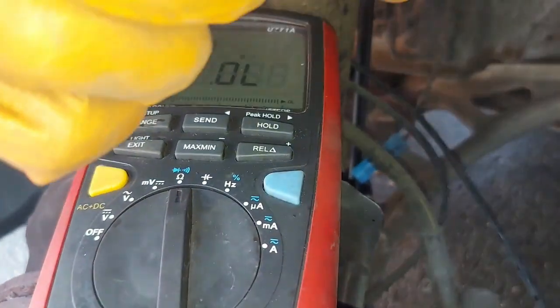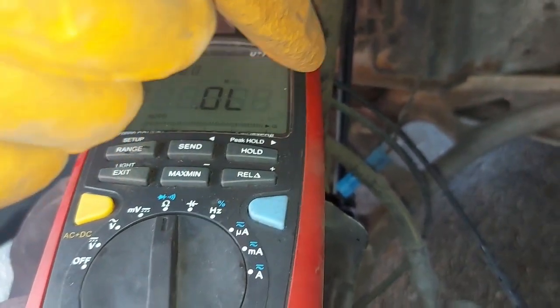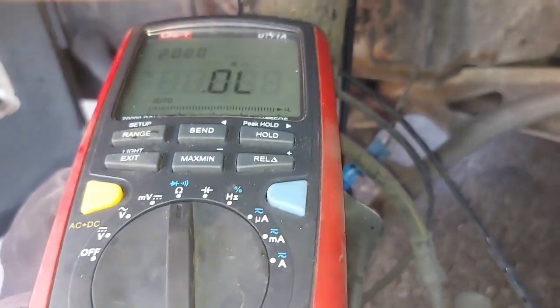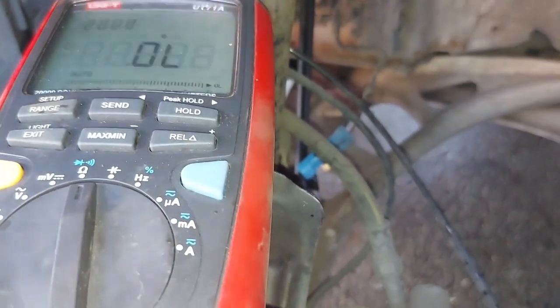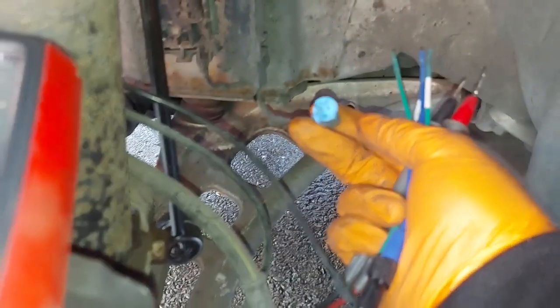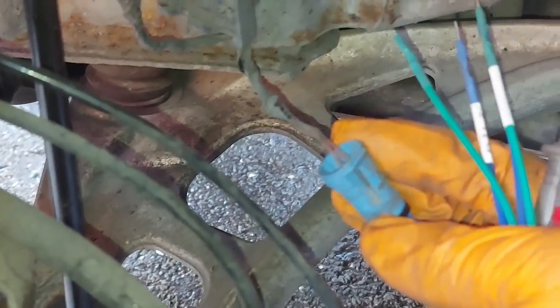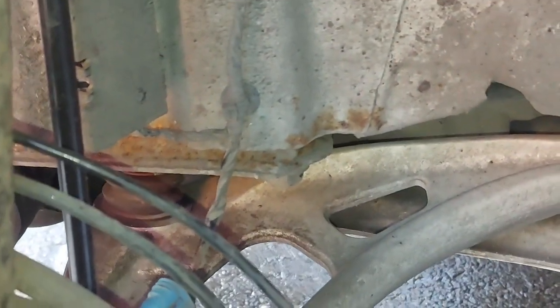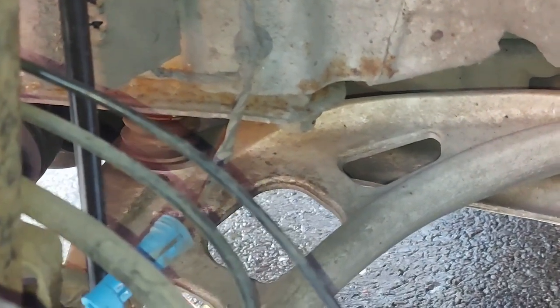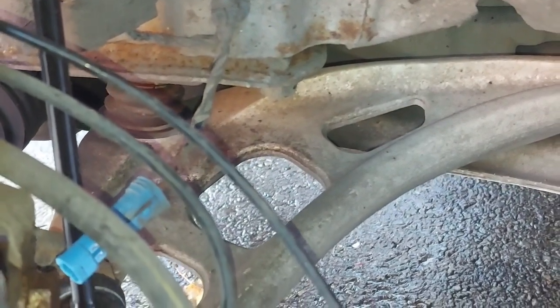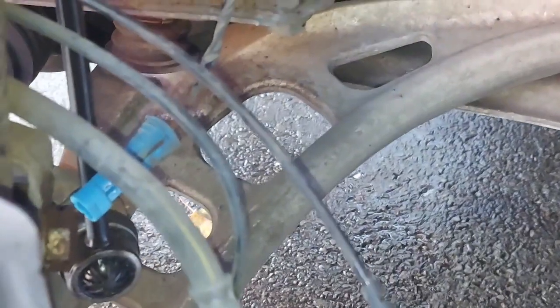So I may want now to check the two wires from here to the ABS to see if there's no broken wire from this side of the sensor going to the ABS. Because if there is a broken wire, that could be where our problem is. The sensor seems to be okay. I don't know whether the 400 and something ohms can upset it to the point that it doesn't read. I'm not quite sure, but I'll investigate that and let you know.